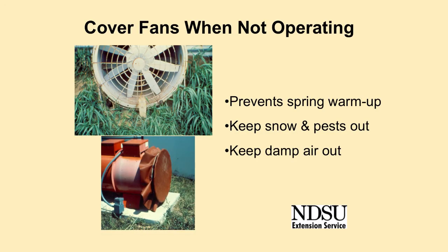Aeration fans should be covered when not being used to prevent grain from being warmed in the spring and summer. Wind blowing into an uncovered fan will warm the grain to near the average daily maximum temperature. Covering the fan also keeps out snow, pests, and warm, humid spring air.